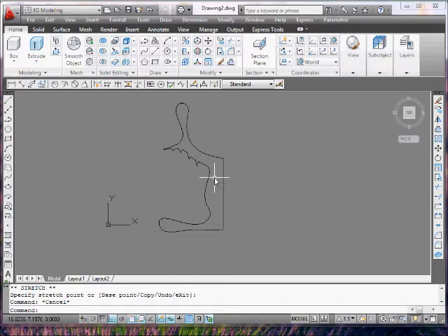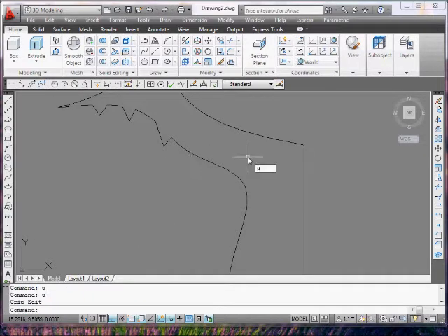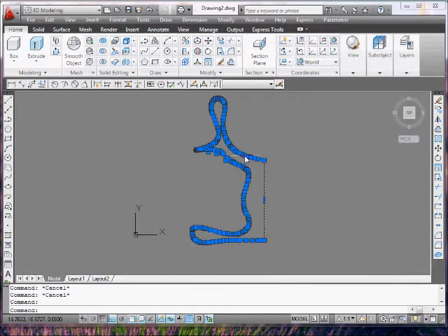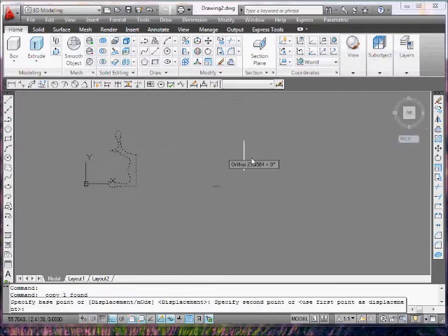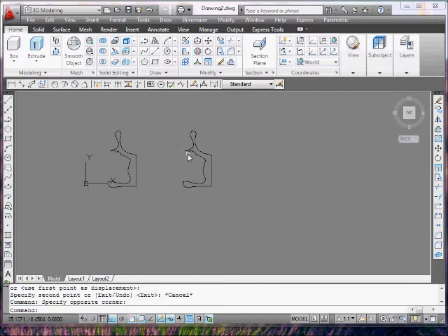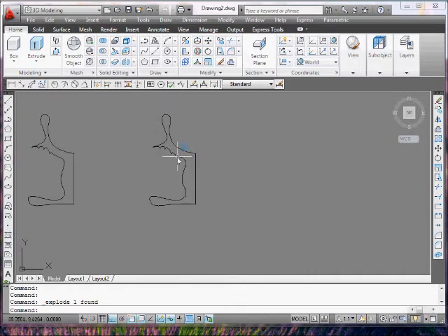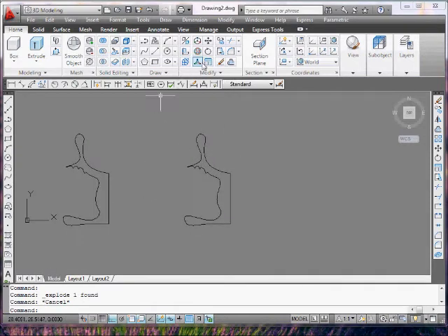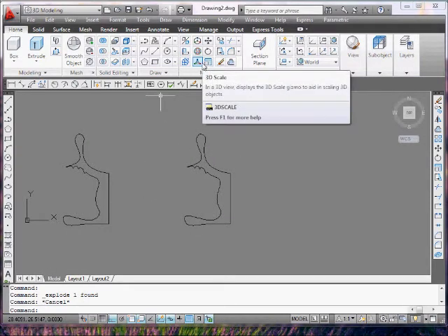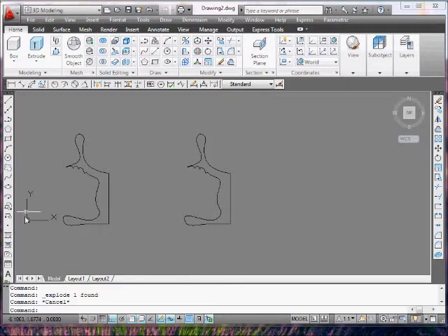Alright, another option of making this into a polyline is, I'll go undo. Actually, I want to keep those. I'm just going to do a copy and explode it so it's back to its original, except now it's not 2 lines, it's 228 lines. But still, it should work perfectly fine no matter how many lines you have, as long as the item is enclosed.